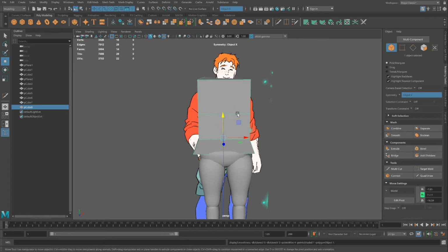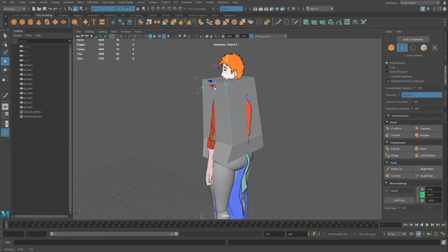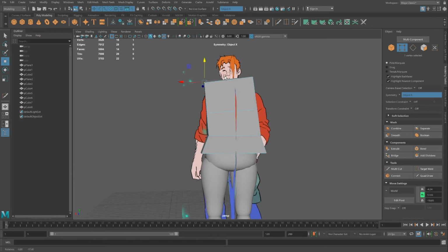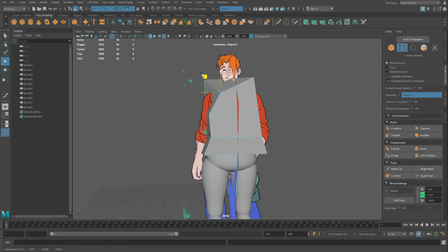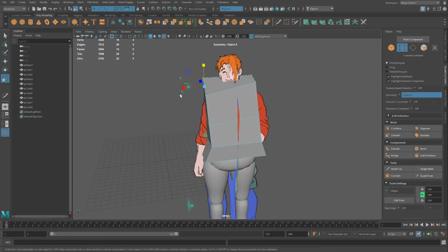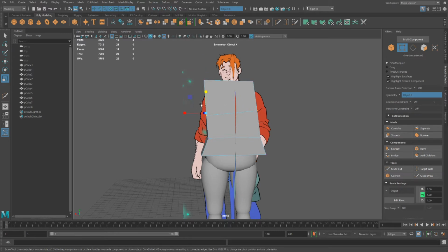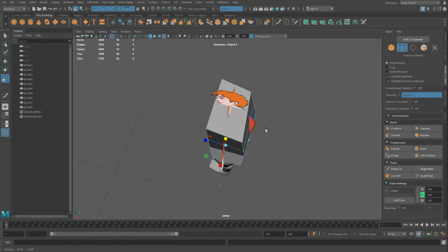So press the 1 key, just making sure things are symmetrical, and they're not. That's okay. I can fix that. In Maya, the quickest way to fix something like this, you can select all those vertices on top and use the scale tool and just scale it along y-axis. Straighten things out. Another option would have been to mirror this object. I might have to do because it's a little skewed.